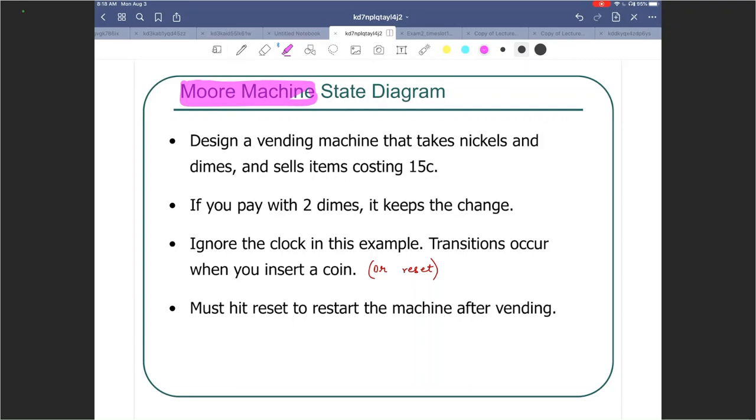The advantage or disadvantage being, if you choose a Moore machine, then the outputs change only when the state changes. With Mealy machine, you can have both types of changes in the output. So outputs could change immediately as soon as the inputs change, or when the state of the flip-flops change as well.